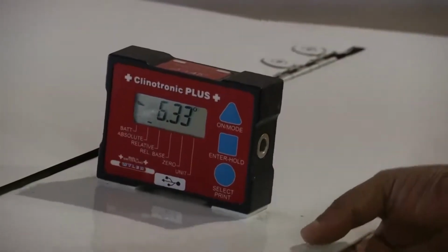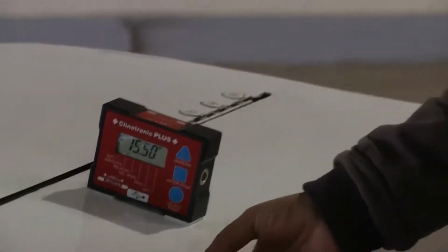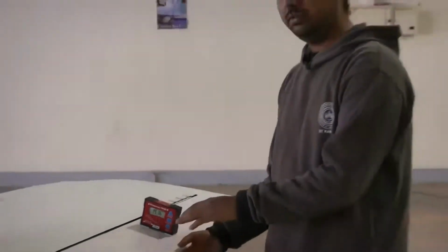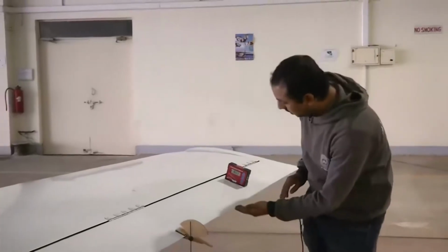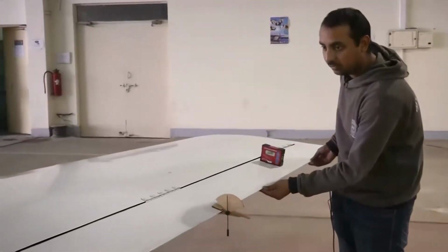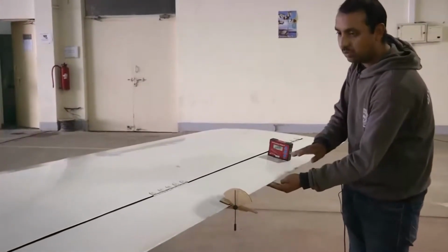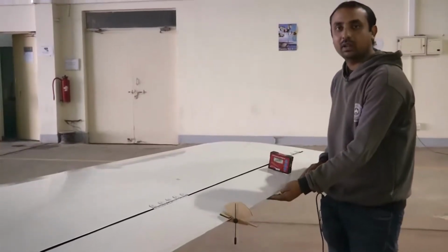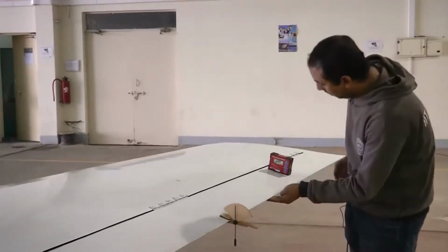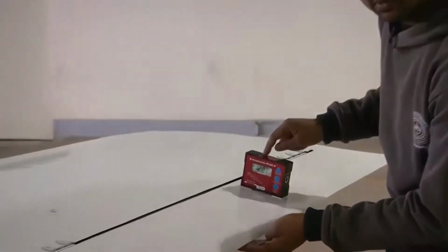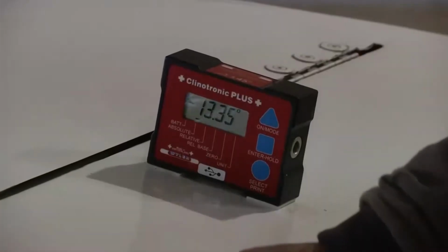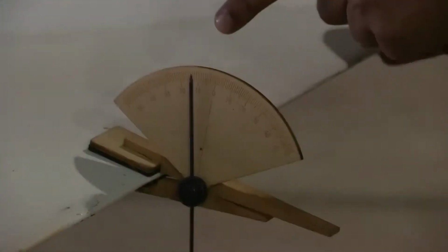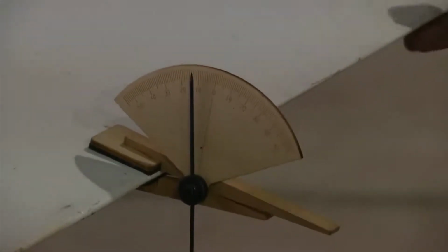Now, in my lectures I have already explained how to determine your reference point. Now, this wing is at some angle with respect to your ground. That's why if you want to take a reference value, say if this is your neutral position or your control surface deflection is 0 here, you are getting a default angle of minus 12.09 degree. Same you can verify with your inclinometer, that is analog inclinometer, it's showing somewhere close to 12 degrees.